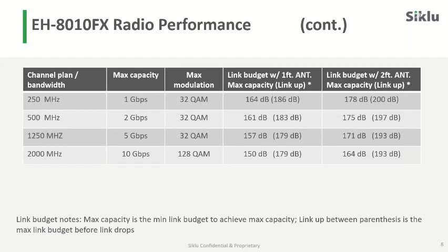In that case, if you have important traffic, maybe some voice traffic or some business customers who are more important than others, then the radio will prioritize the priority traffic and make sure that even though the capacity would be reduced on the radio link, the priority traffic will still be delivered across the radio link. So that is why we recommend to most of the time enable QoS.